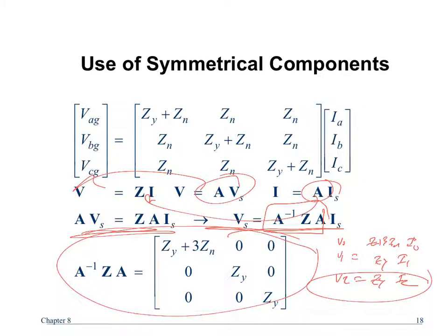Does V2 give any care or consideration about what's happening in the positive sequence network or the zero sequence? And vice versa, right? So this is showing me that I've decoupled my networks. In a balanced system, the networks are completely and entirely decoupled from each other.